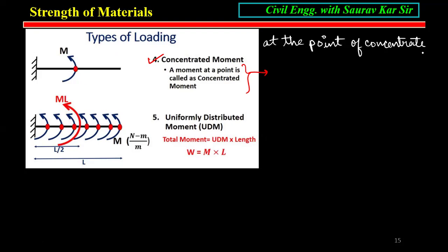Clockwise or anti-clockwise doesn't matter. At the point of concentrated moment, for example, at a point instead of load, there is only moment. Then the bending moment sign changes. The bending moment changes. Okay. No change in shear.